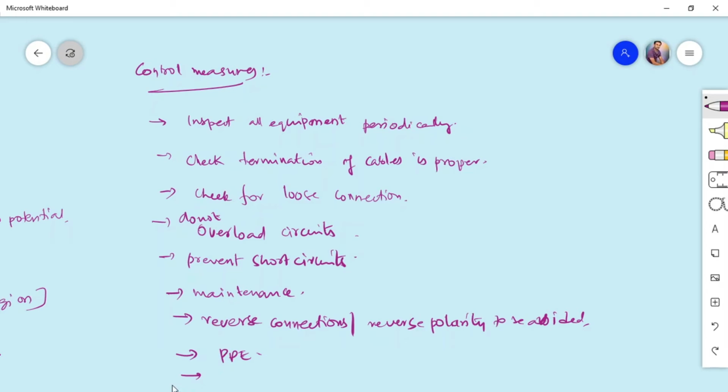So what we need to do is make sure we discharge the stored energy by a discharge rod. We will have a discharge rod, especially for high tension lines, or when you are working in power plants and circuit breakers. We have to discharge the stored energy. So when we switch off the power, go for discharge directly.